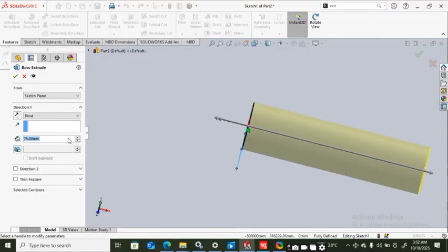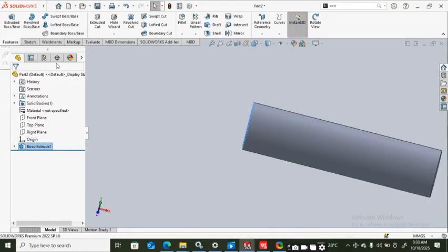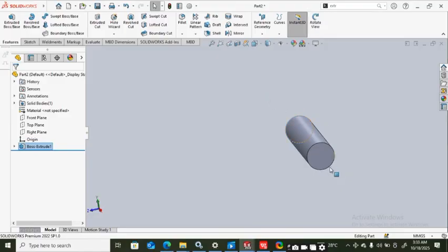But if you want to get it to a precise point without dragging your arrow, you can just click 80. Once you click 80, then you check this place, or you press enter on your keyboard. So I'm going to press enter on my keyboard, and then it is now in a 3D model. So this is actually what we have. This is our first cylinder, right?